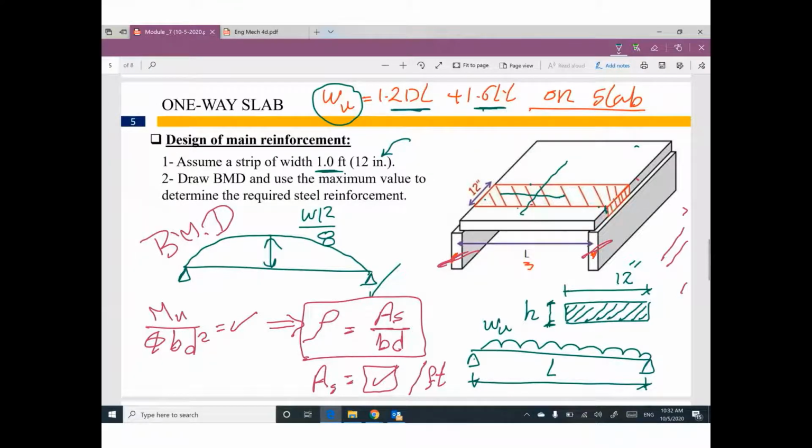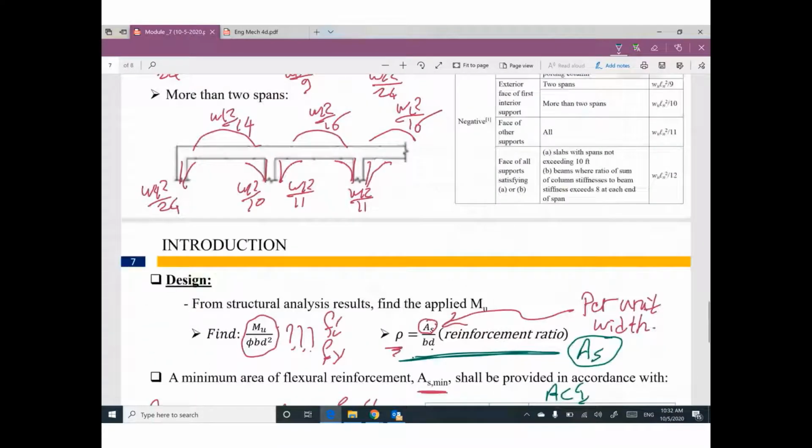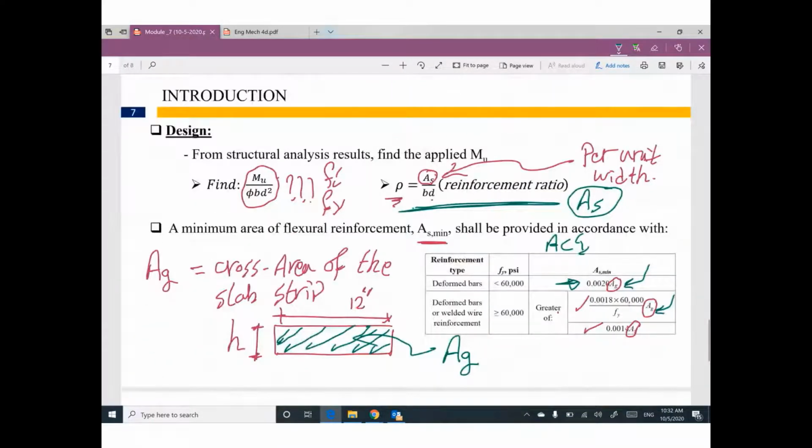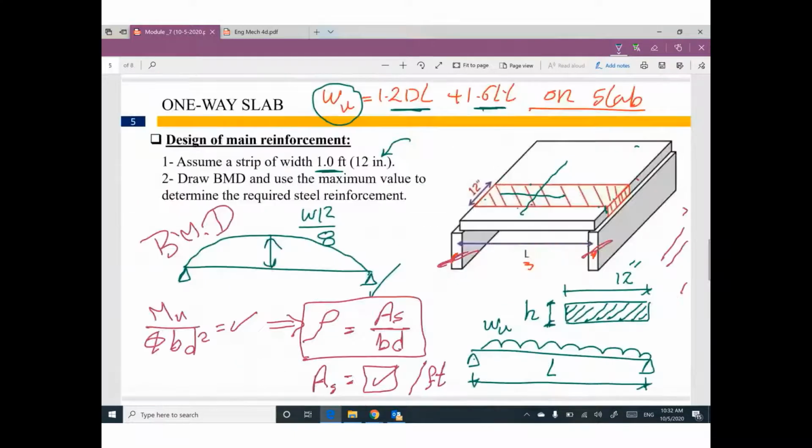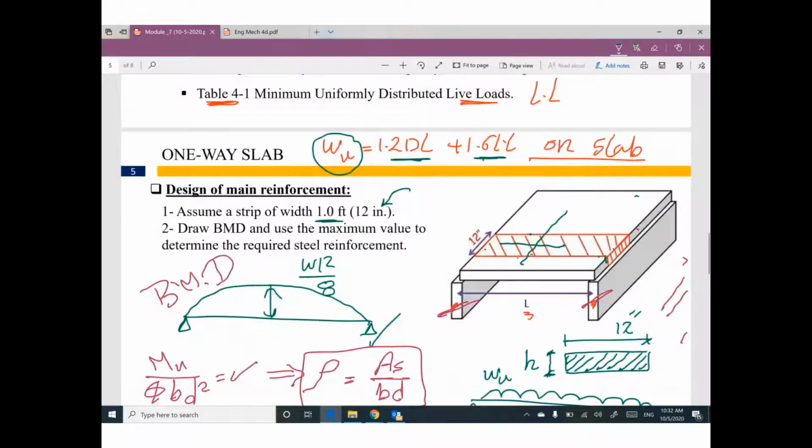My question one more time. You designed the slab and you figured out how much steel reinforcement is required. By the way, your area steel, for example, equals 5 inches squared. So I can figure out this 5 equals how many bars and what is the size of the bar. This number and this spacing will be every 1 foot because you are talking about a unit strip. My question is, will this steel reinforcement be placed in this direction, or this direction, or both of them?